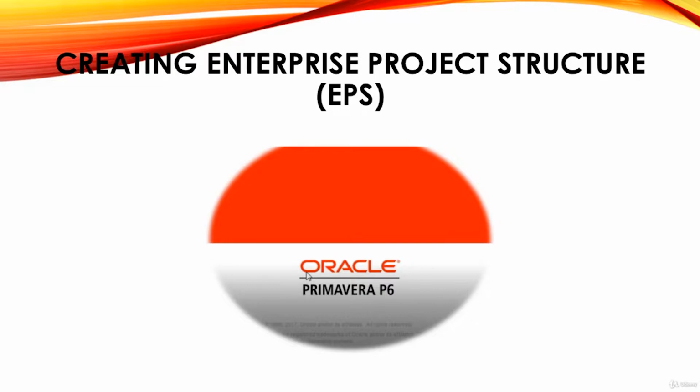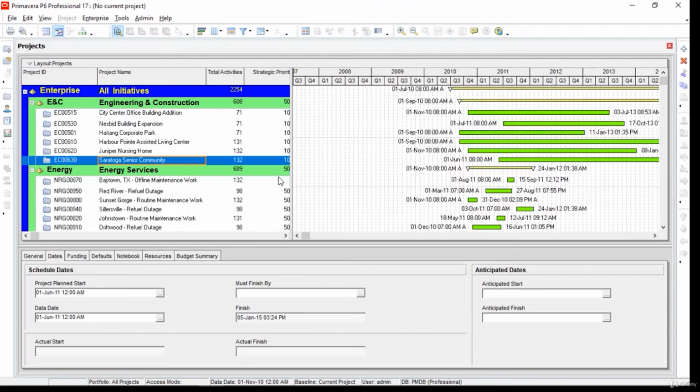In the previous lesson, we have already defined our user and admin preferences. So now we are ready to create an enterprise project structure and then can create and start working on our new project. Please remember, in simple terms, the enterprise project structure EPS creates a database of projects similar to folders, and each EPS node can be further divided into multiple levels.